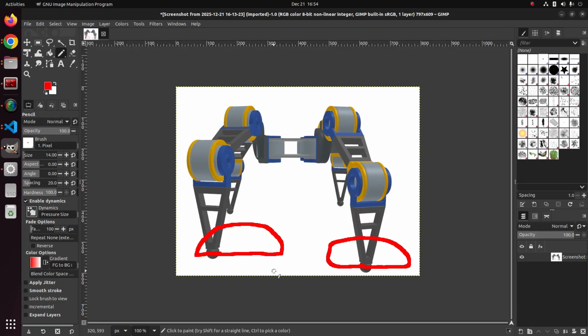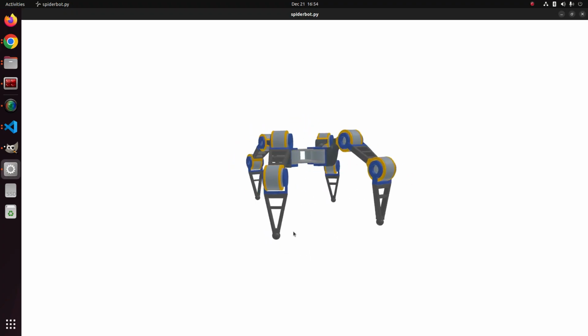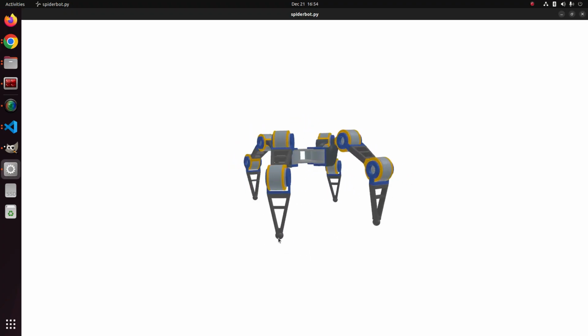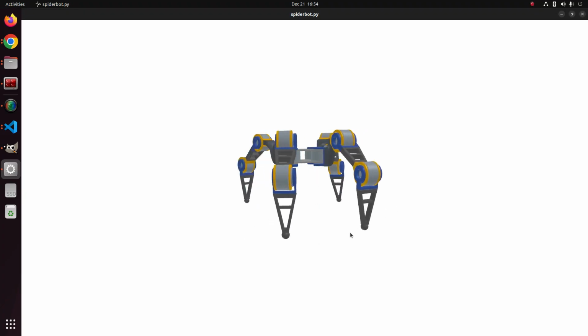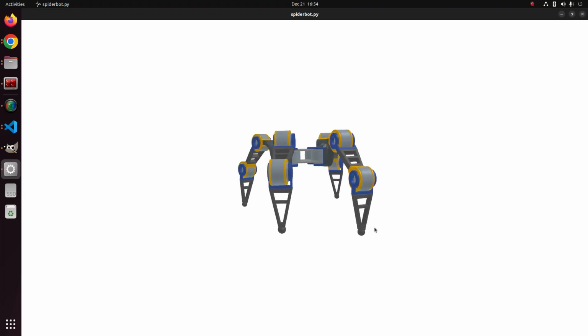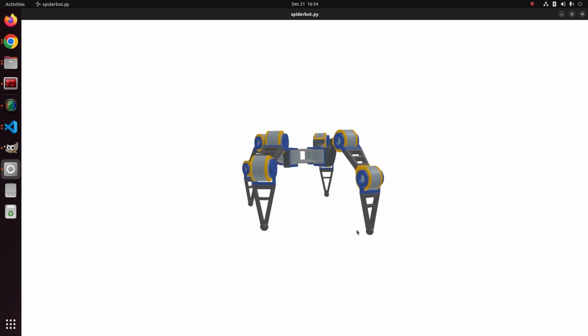So by generating these trajectories for each foot, we can force the robot to walk like the animation here. So that's all that's happening here. This leg is moving straight, and then we follow a semicircle up like this, and this is doing exactly the same motion, but it's offset by about 15, well, half of the number of frames of the animation like this.